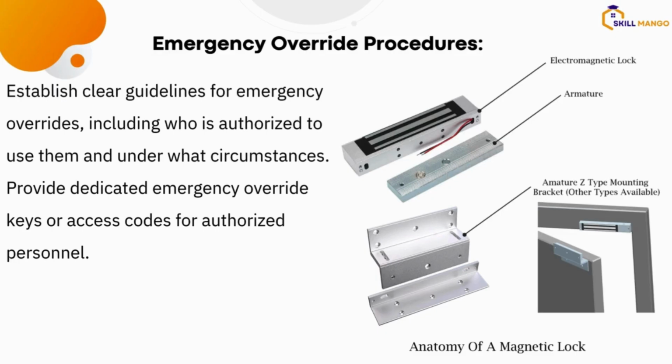So I feel like you need to understand this fact. From the lock itself, there will be a cable that will go all the way to the reader. Then on the other inside part, there will be another cable that will come from the exit button. Then there will be a cable that will come for the power supply.